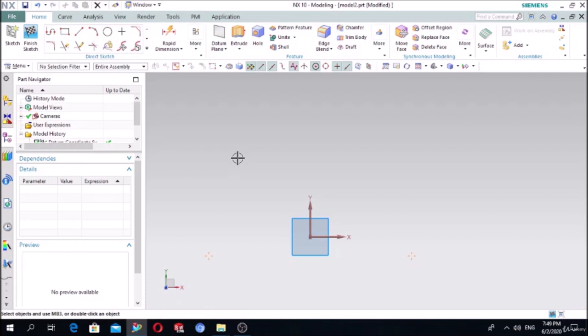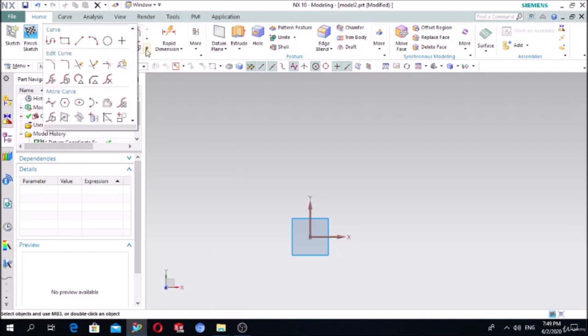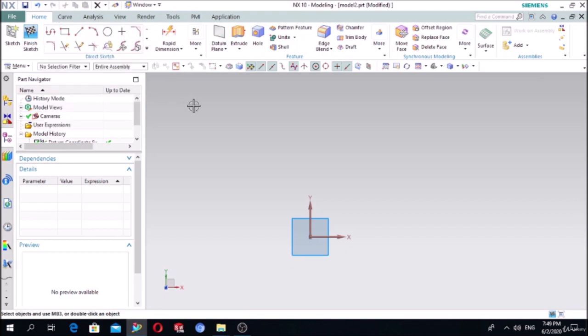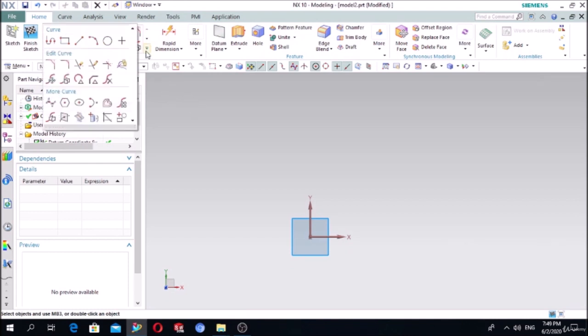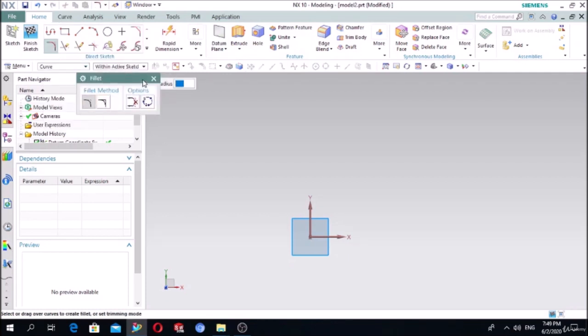Next, if you open the draw commands as we learned in the first lesson, we left some functions remaining here. We will see these functions today. The first function we will learn today from this bar is Make Fillet. Here there is the fillet function. This command rounds a sharp corner created by the intersection of two lines, arcs, circles, and rectangles, or polygon vertices. To activate this, press this one, and it is activated. This is the fillet function.